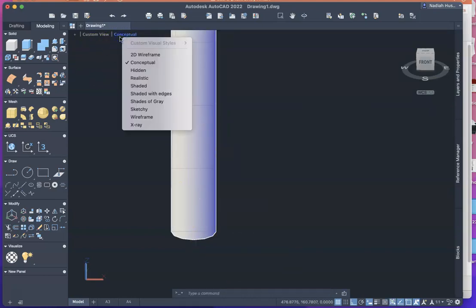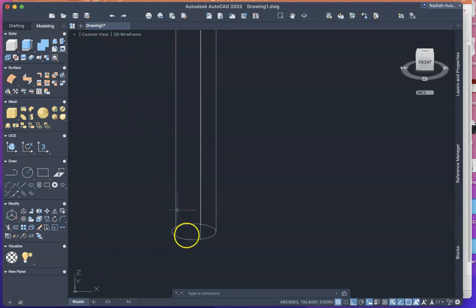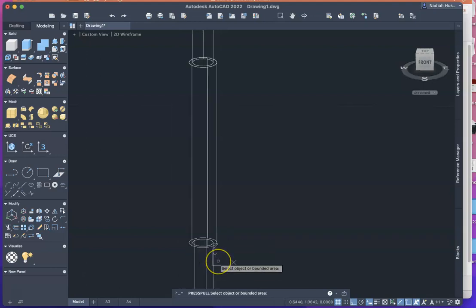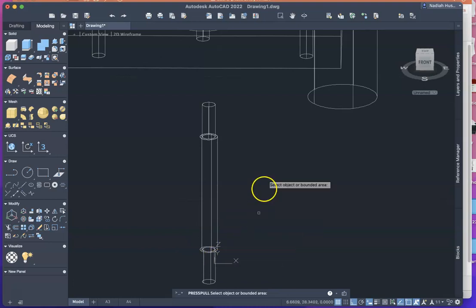I'm not going to do 3D mirror because I need to find time to learn how to do that, which I don't have right now. So I'm going to specify a circle down here, sorry, with a diameter of 1.85, and then I'm going to press pull this or extrude this by 5 again. Okay, so hopefully that is it.